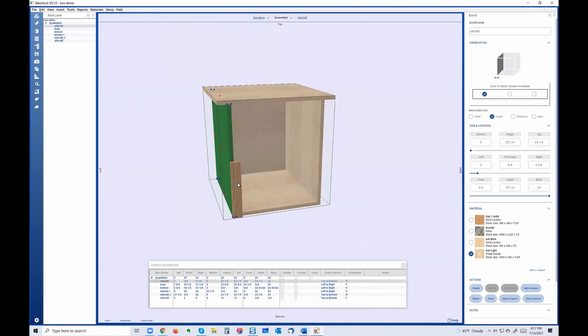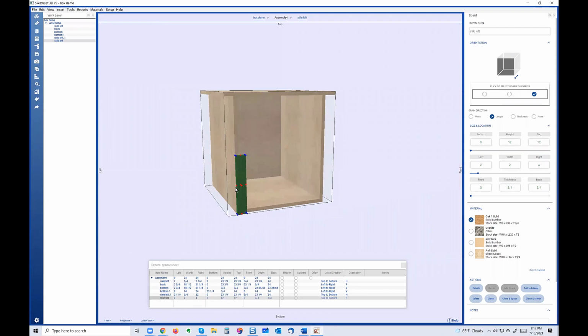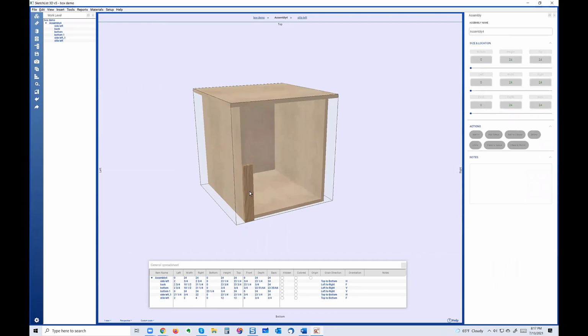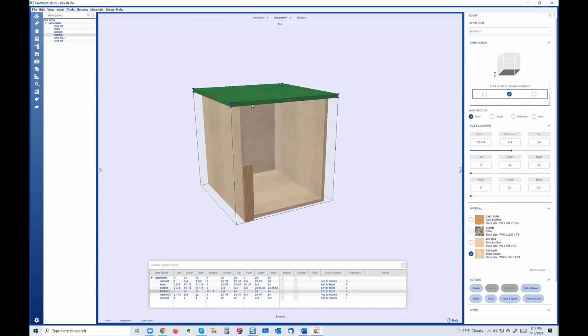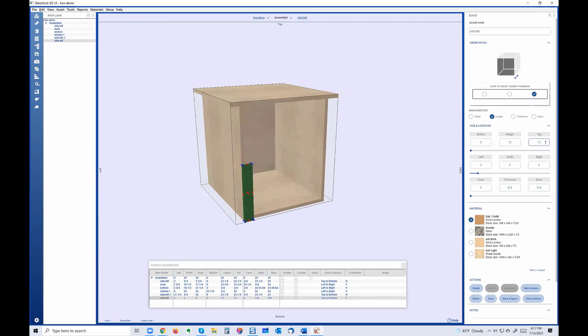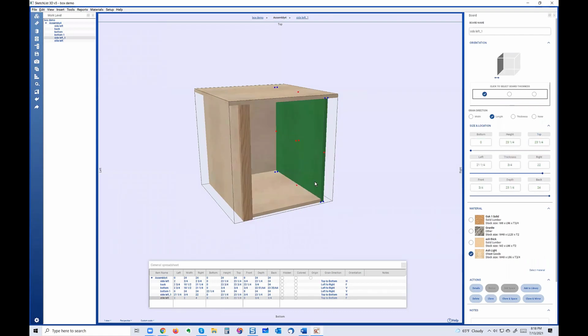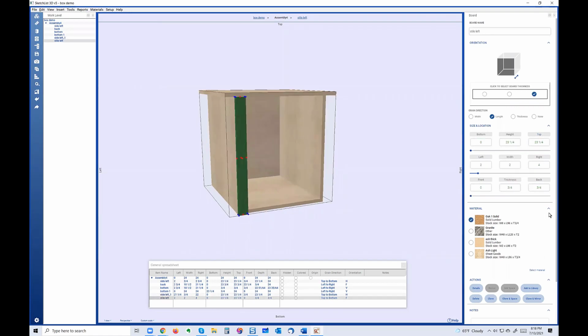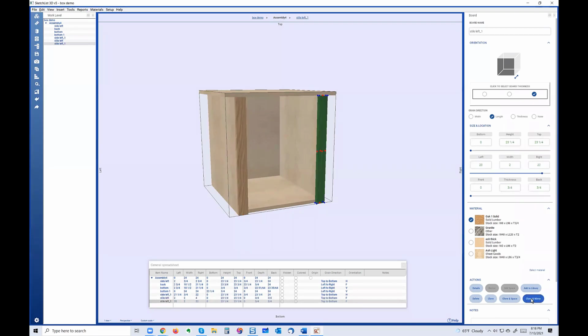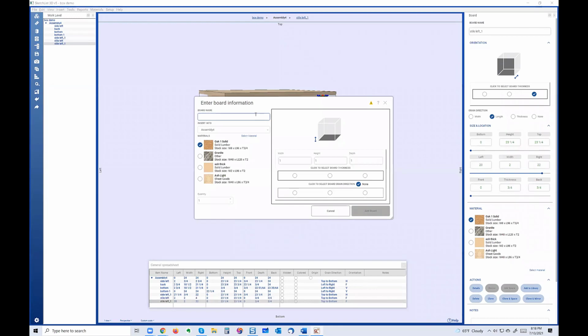And then here, again, there are different ways I can look at that. So the bottom of this is 23 1/4. So I'm going to make the top 23 1/4, like that, changing the height. Just like this. Come here. I'm going to clone and mirror that one. That's one of the utilities. It's a time saver. Just put it over there. I'm ready to put in my rail. Same thing. Insert, size, and locate.